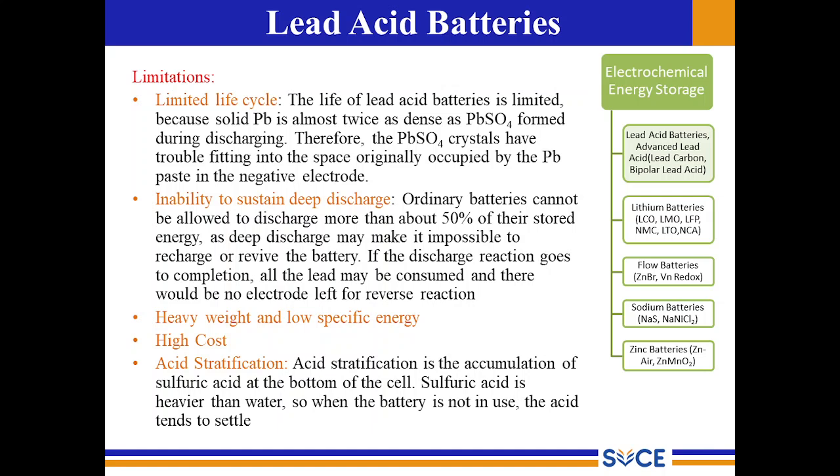And the last one is acid stratification. Due to the consumption of the sulfuric acid, it results in the accumulation of sulfuric acid at the bottom of the cell. Sulfuric acid is heavier than water. So when the battery is not in use, the acid tends to settle down.